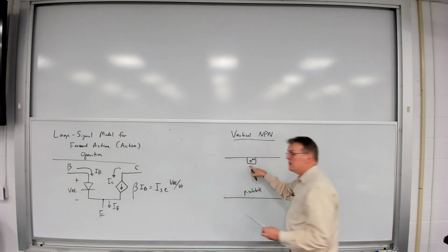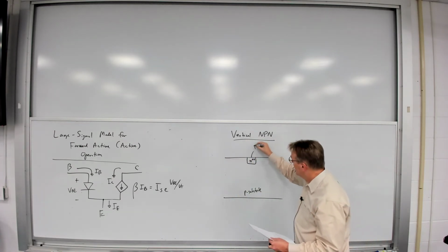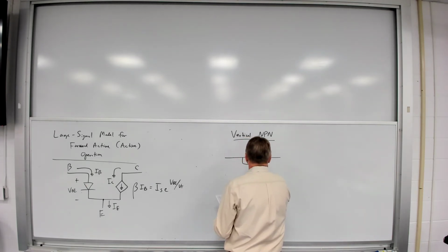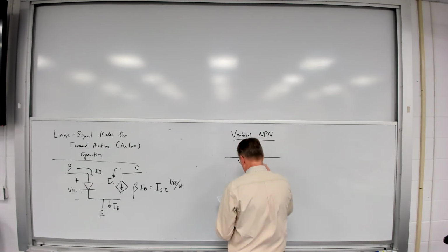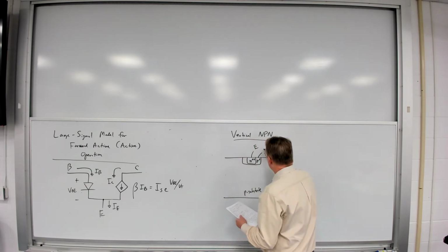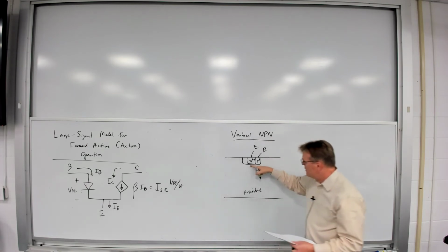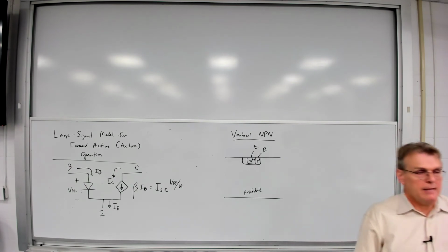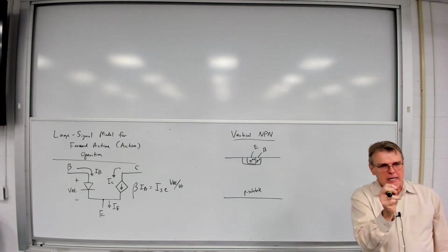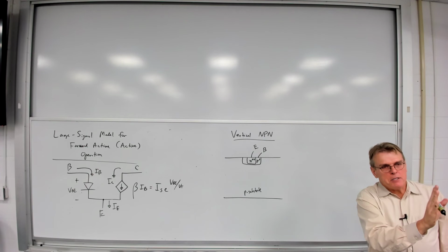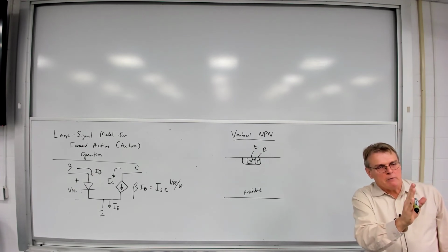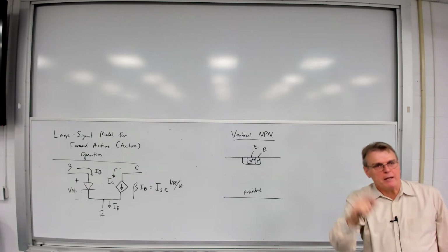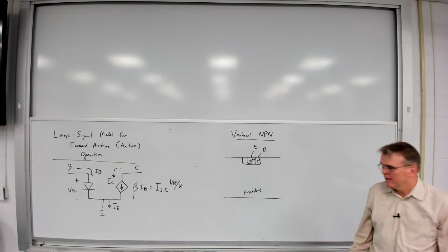and then we're going to have a very highly doped emitter. And then a moderately doped base, and notice right underneath the emitter it'll be very thin. That base region will be thin. And that's deliberate. We want that base region to be thin because we want to make it very easy for the carriers, the excess electrons, to drift through that base and be captured by the collector before they can recombine. And so the thinner the better.